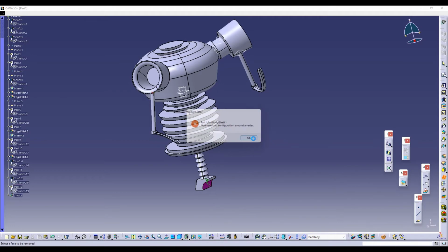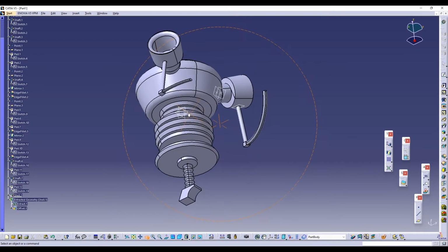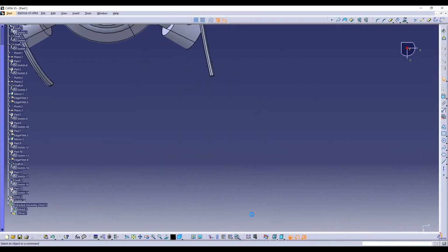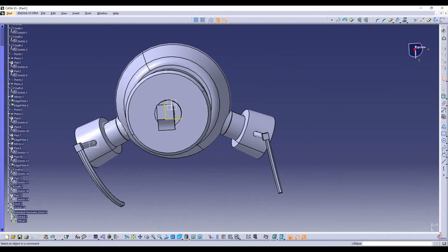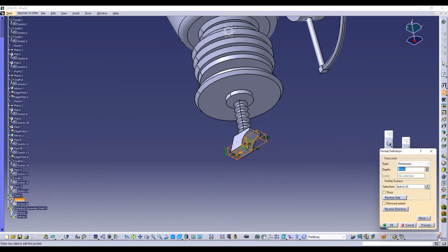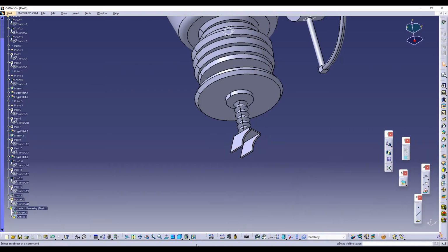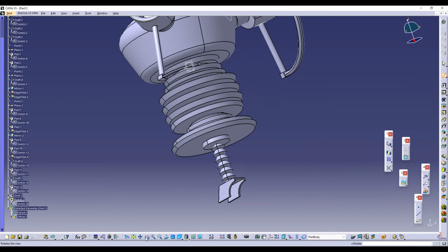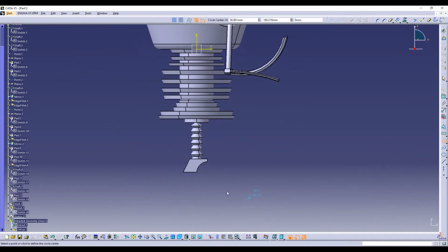It's not happening. We'll create a hole now, downside, by creating a sketch surface. Click on downside. We draw a rectangle. Then done. Then we'll try the hole option, pocket option. We'll pocket this out. Okay, it's done. And let's try to make a wheel now, a down wheel, in which the robot is going to move according to the decisions given by the operator.